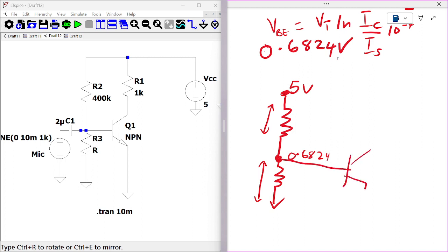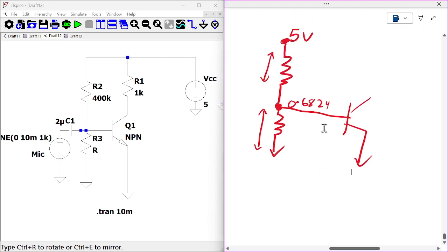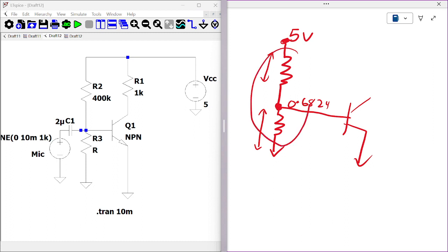Now before we do that, let's look at something which might be very interesting to us. Now assuming I just split the resistors into two. So first of all, per your input impedance, you want the value of these resistors to be big enough to satisfy the required input impedance that you want.